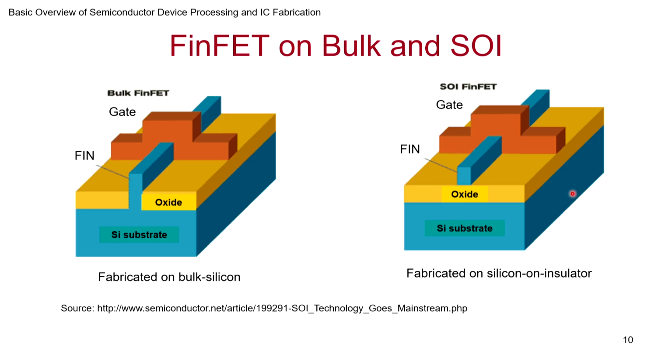If you can get some really high quality but very low cost silicon on insulator substrates, this would be the one. Otherwise, this may also work, as some companies have followed. So I hope you get a feel for how the device is. One side of this fin is source, another side of this is drain. Of course, all MOSFETs are typically symmetric, especially because you may need it for pass transistor applications.